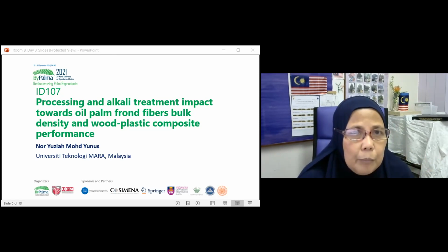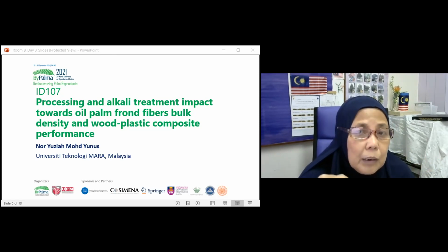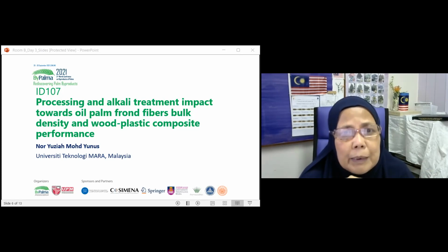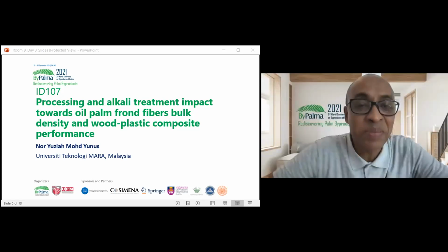And normally in production, if you see what they do nowadays for wood plastic composite, they are looking at melt flow index between 10 to 12, which is very common for this product, and then they will come up with about 60%, 70% fiber inside there. Thank you very much.